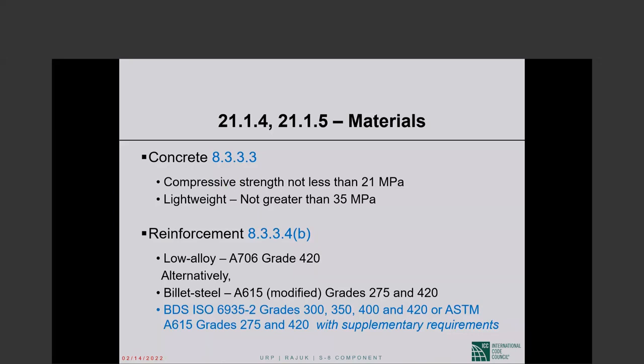3,000 psi, 3 ksi. Okay, lightweight concrete, we now have an upper limit which is 35 MPa, 5 ksi.